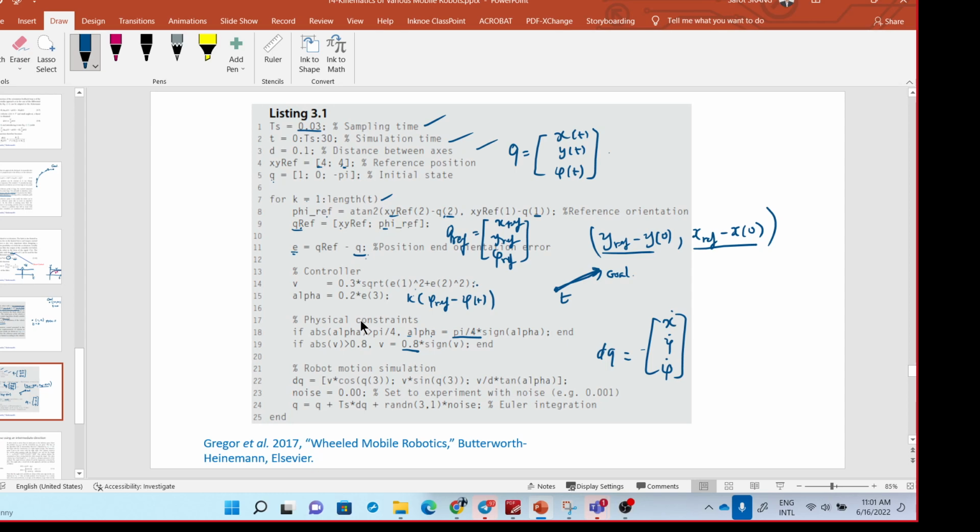But anyway, I just give you the idea that you can try to tune it using a big value and then reduce to smaller. For simulation you start from big, but for experiment and implementation you should start from small. It's okay to take longer to reach the goal, but not to have it move in a chaotic motion and break down the hardware. Okay.